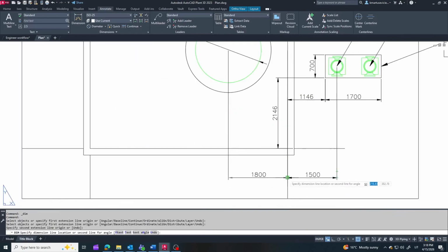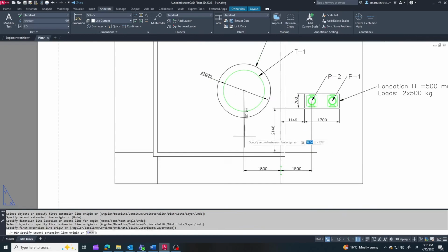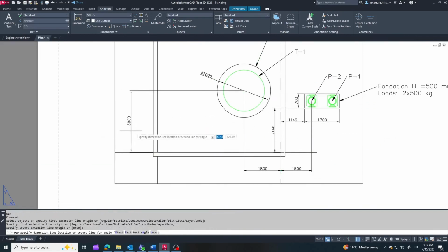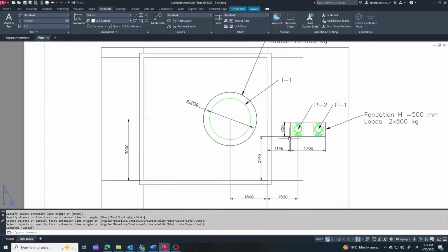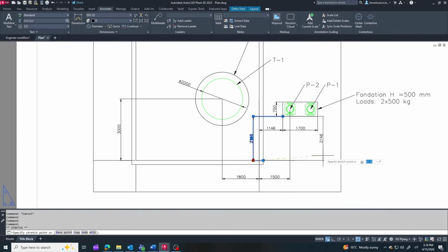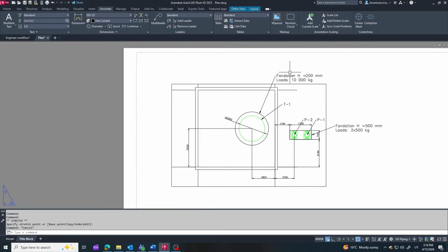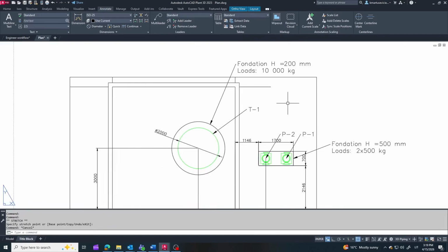One more important thing, fixation points. You need to know where the equipment is anchored. For example, bolt locations for a pump, or support legs of a tank. If this is an early stage task, and the exact equipment is not yet defined, detailed bolting is not necessary. But once you have real equipment, you must specify bolt hole sizes and their exact positions.